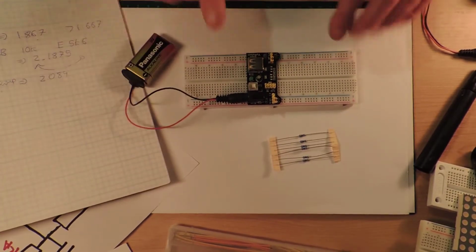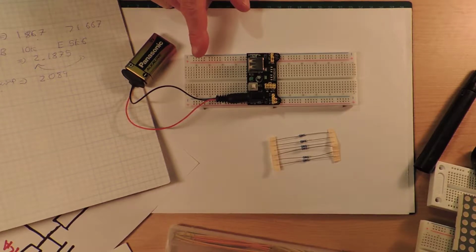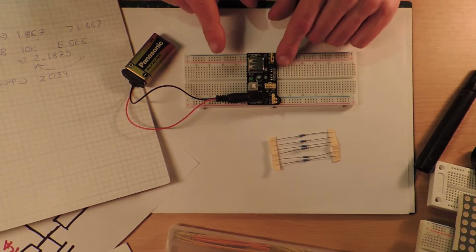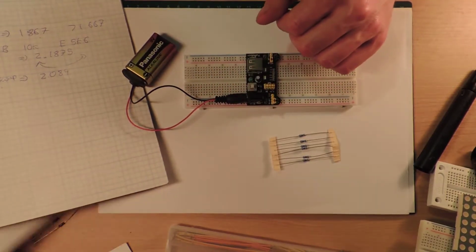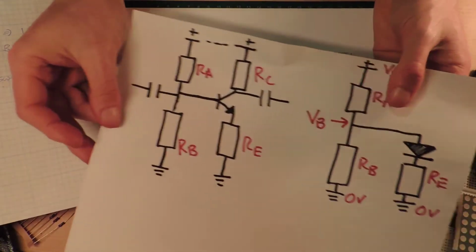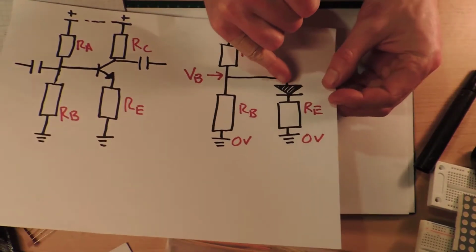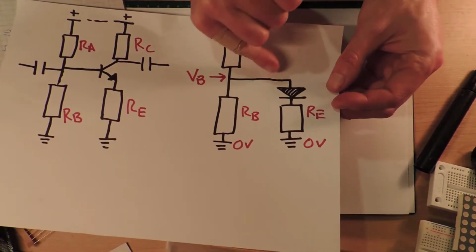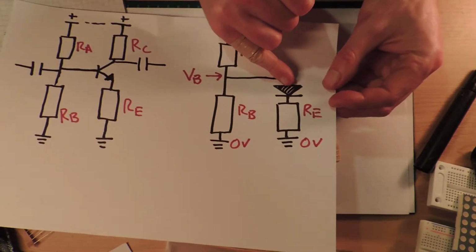When I put this into that online circuit simulator tool, it uses a much better model of a diode, and of course the voltage drop across a diode is not constant. It varies with how much current's going through it, and so a lower voltage drop will allow some current through.